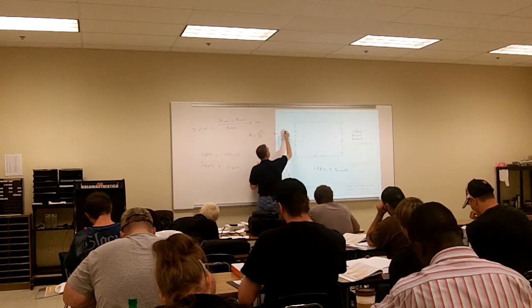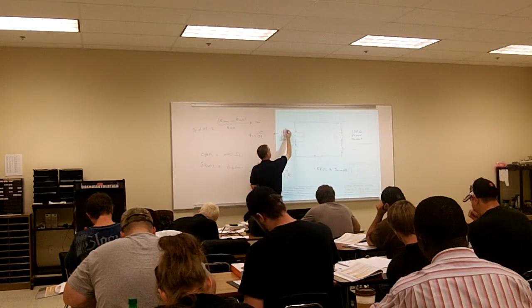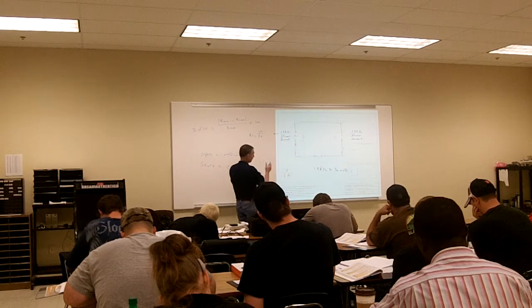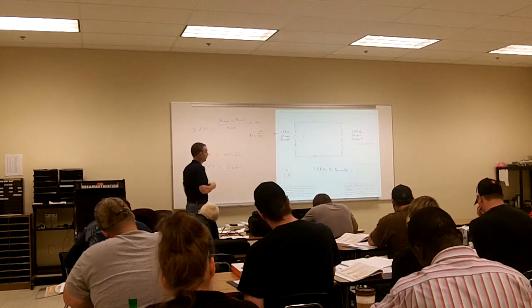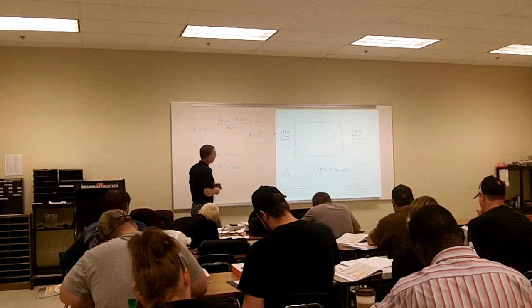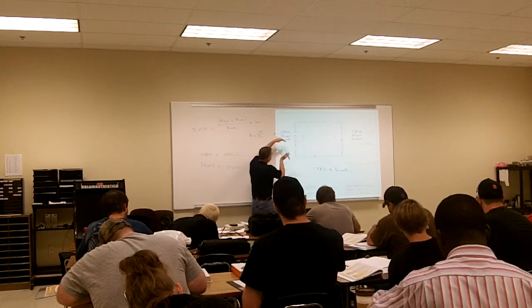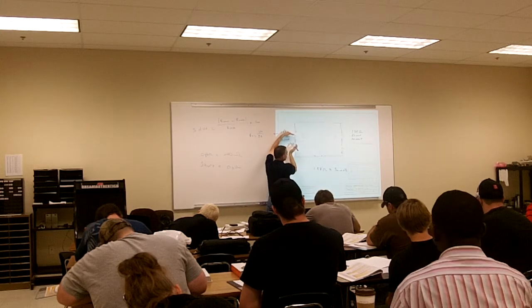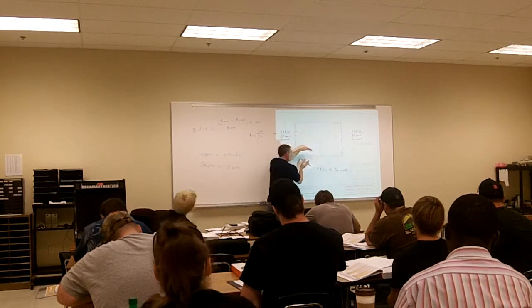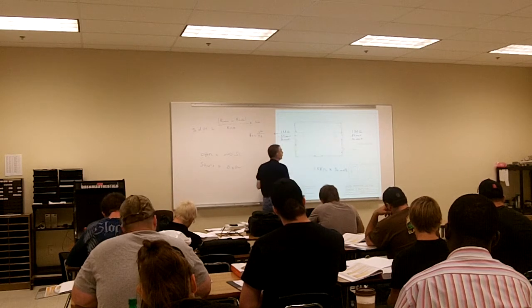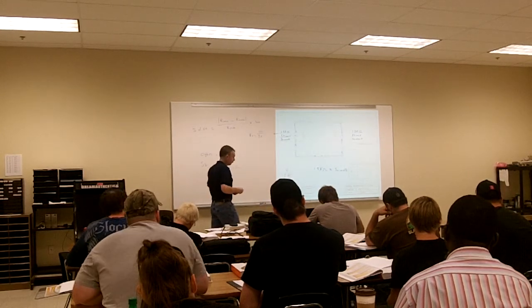You said that the total sum of all my resistors in a series circuit is going to equal my total resistance. And since I only have one resistor in there, that's going to be my total resistance. Yep. So if I'm the power supply and I'm looking out at that circuit, I'm seeing this much opposition to current. I'm seeing that 1.8 kilo ohms out on my load.